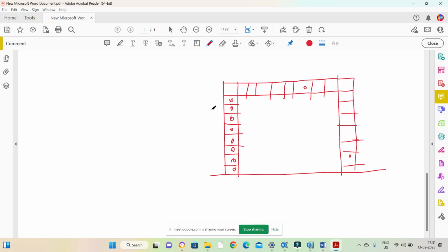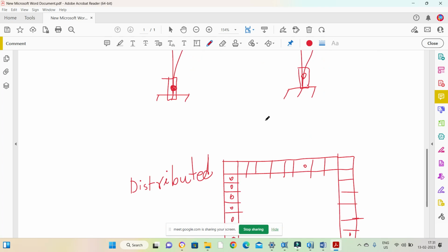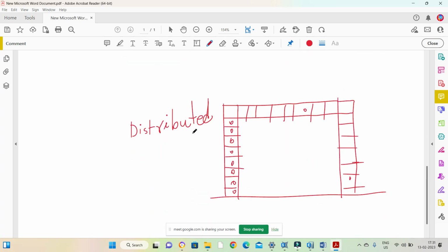And this is called distributed plasticity. Sorry, I could not recall this one. So this is distributed plasticity. Your nonlinear definition is distributed throughout the length of the member, with the expectation that the structure can fail at any point, means at any particular point within the whole length of the member. So this is the difference between concentrated and distributed plasticity.